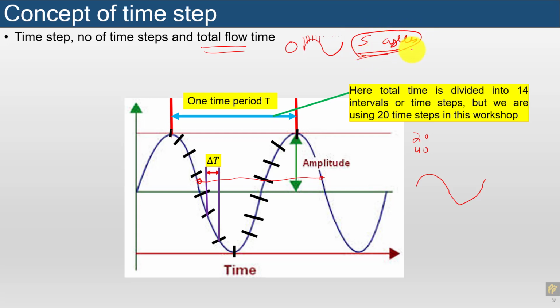To find out the frequency, we are going to apply the fast Fourier transform on some parameter, like the lift coefficient, or maybe we set a velocity monitor at some point. This is going to be the y velocity, because y velocity is not changing in normal uniform flow, but in the case of the vortex you will see that there is a y velocity as well. Okay, x velocity versus y velocity.